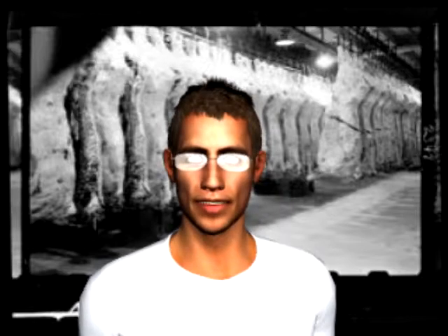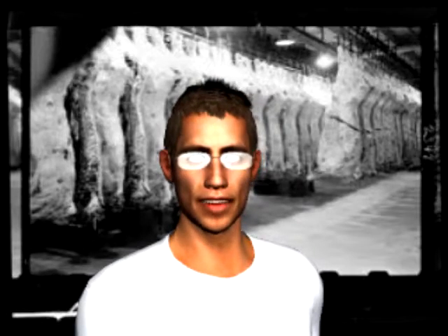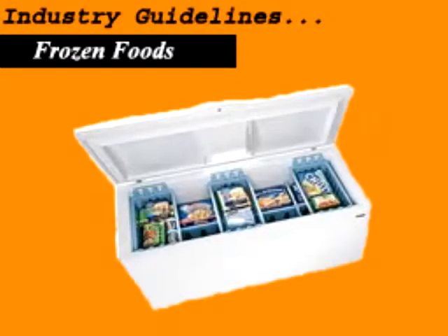There may appear to be a case for setting all freezers to the lower temperature of -24 degrees centigrade, but foods at this temperature do take significantly longer to defrost, and many lighter quality foods, for example some pastries or sauce-based dishes, can be damaged by freezing so deeply. It is important to note that you should always consult the manufacturer's instructions with respect to the freezing capabilities of your piece of equipment.